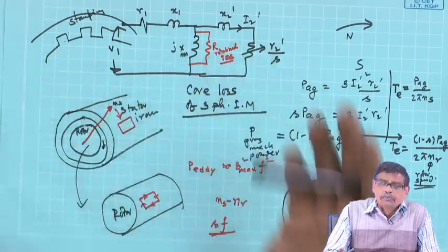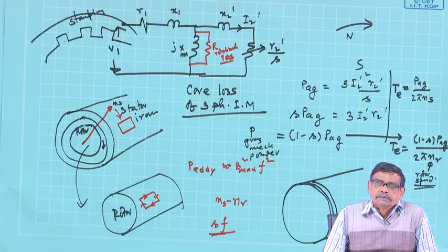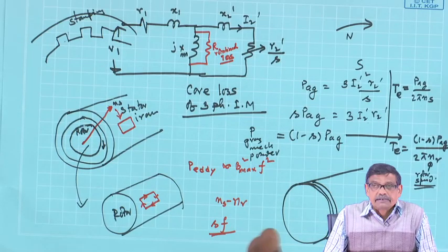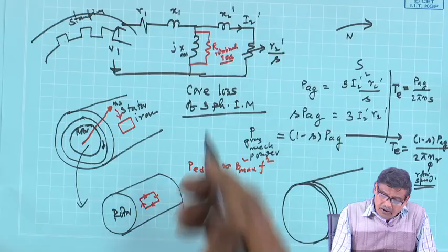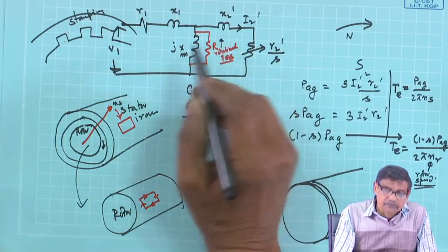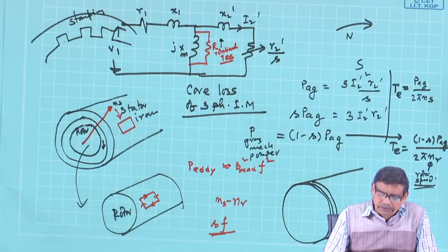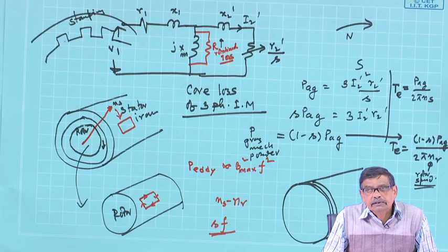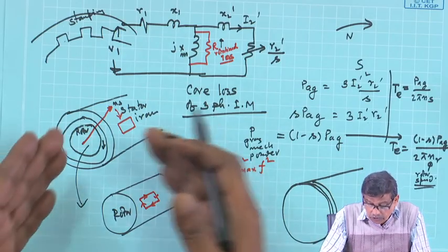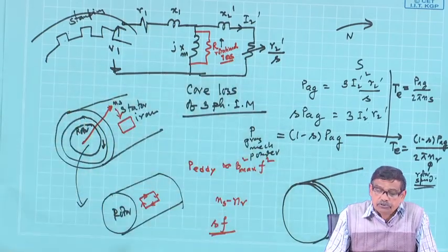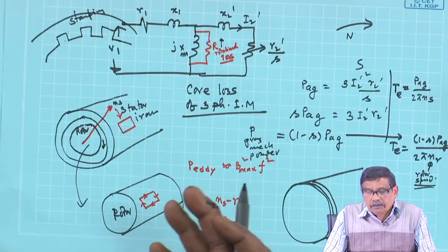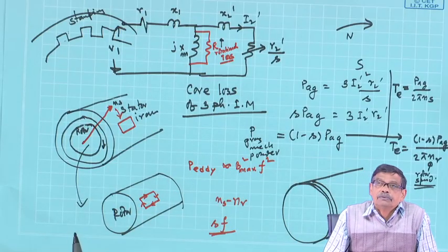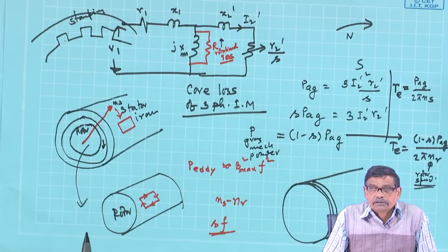So, stator is to be definitely laminated, okay? Thin plates to reduce this or to make this high. So, you take care of that, try to reduce the rotational loss as far as practicable by using stampings while constructing the stator iron. It is not a solid block of iron. If you use solid block of iron, iron will become too heated up because of eddy current losses.